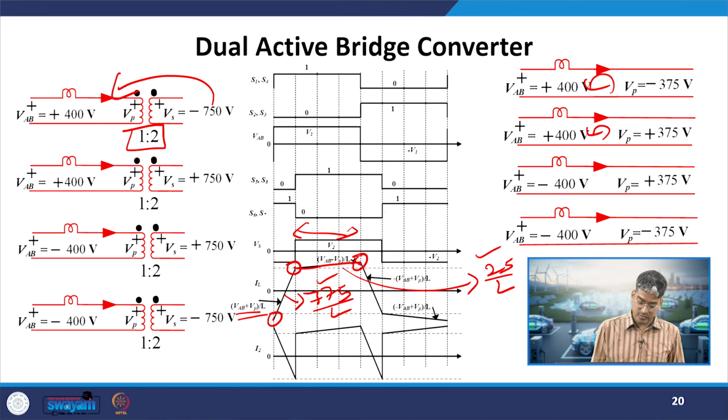At the end of mode 2, it will reach the maximum positive current value. So, what changes have been observed? In mode 1, where it was experiencing 2 times the supply voltage, now it has experienced somewhat lower voltage, and in mode 2, where it was experiencing 0 voltage, it is experiencing somewhat positive voltage.